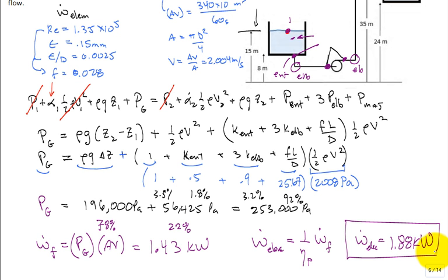But the minor losses in a lot of cases are negligible. In this case, it's negligible. But sometimes you'll have a lot of fittings and contortions and reductions and expansions and not many straight runs. In those piping systems, minor losses are major. They add up. Yes, sir.